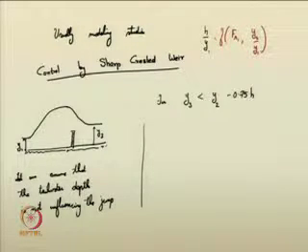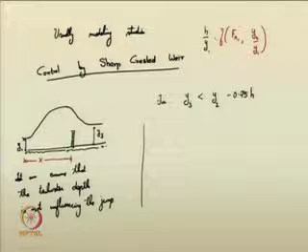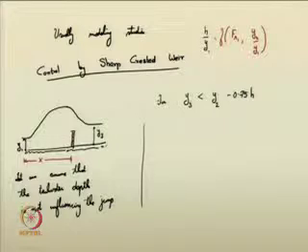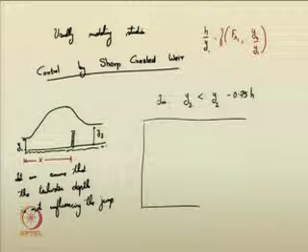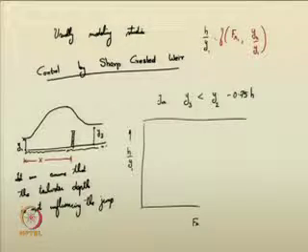Again, how do you define this situation? Now, y2 we can't say is exactly measurable, and y1 is the more appropriate term that can be measured. For designing, we want to know at what distance from the beginning of the jump we should provide the sill. So, this x is the important parameter that we need to design, isn't it? So, that way we can suggest the following relationship: we can devise curves of the h by y1 ratio with respect to the incoming flow Froude number.